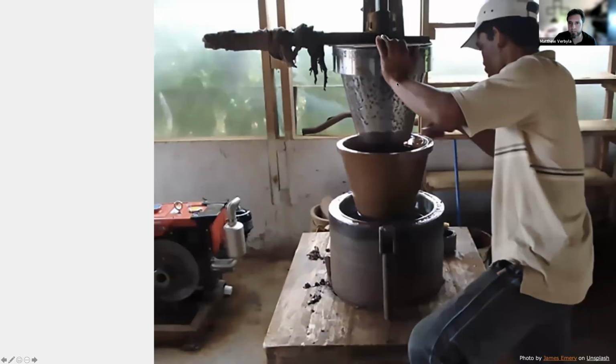They prototyped that ceramic filter and figured out how it can be made easily with local resources, local labor, in settings where there's no electricity. How does the design need to change in order to adapt to local production facilities and the ability to make these things on a large scale? They eventually added things like a silver lining on the inside of the ceramic filter, which provided extra disinfection capability for pathogens like viruses that were able to make their way through the filter, but with the silver lining, they would get killed off in the process, right?